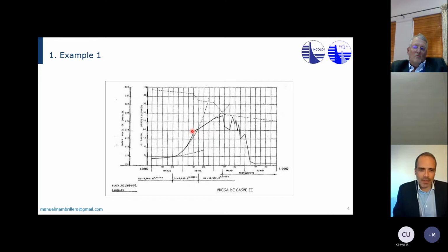And you can see that they managed to change the trend in mid-April, even though it was still an ascending trend. And by mid-May, so like 1 month of grouting works, they started more or less to tackle the issue. You can see that seepage rates dropped, then they went up again, up and down, but eventually by early June,